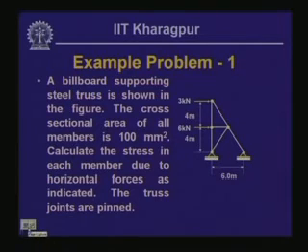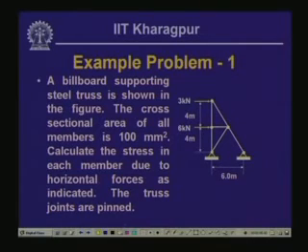Now, by stating that the truss joints are pinned, it means that the forces which are getting transmitted in each of the members are purely axial in nature.